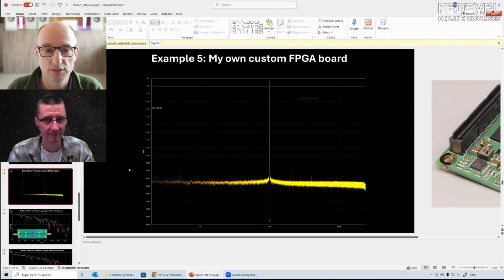this off-the-shelf stuff, it's very often not designed for EMC. If you also just look at the connector, they use a ground connection every 20 pins or something, or 30 pins. So the return path there will always create large loops.